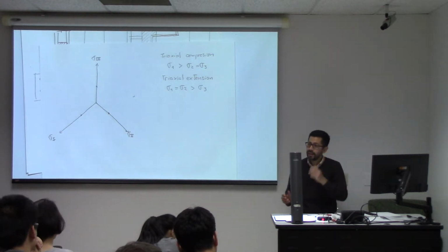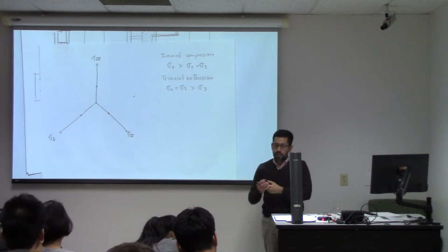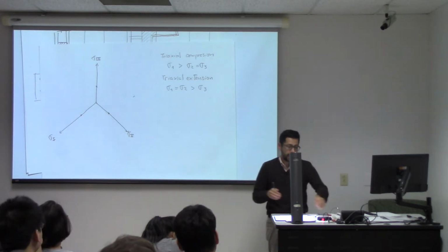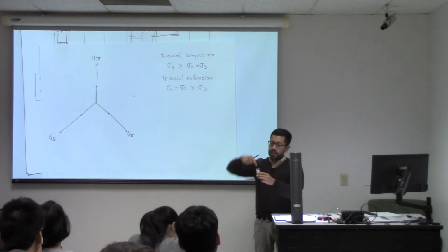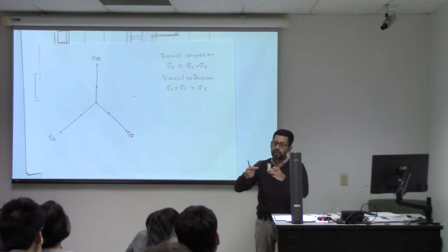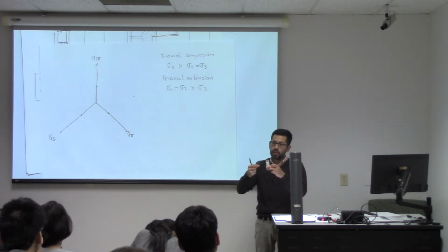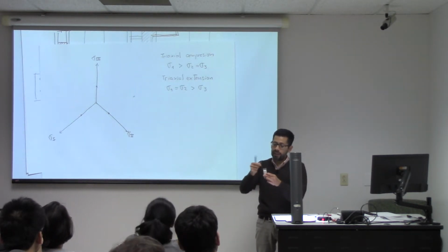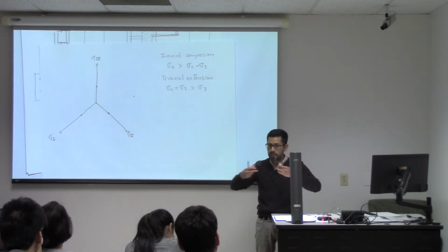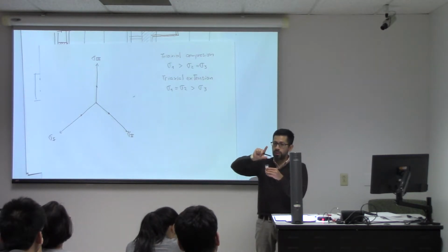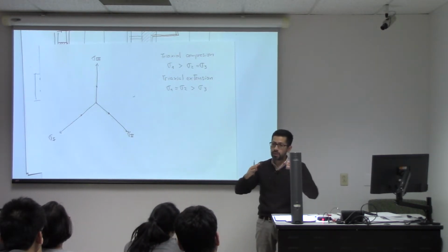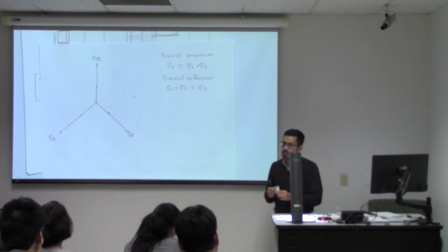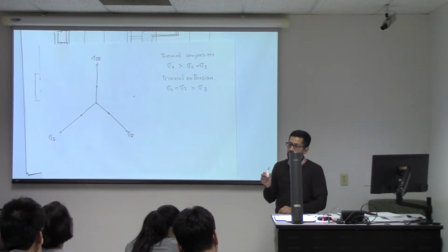So in this case, if I grab this rock in this direction, the stress is going to be lower than the stress in this direction. So you could run such tests and fail this rock by increasing so much the confining pressure, without putting any stress on this side, that it's going to fail by what is called triaxial extension. And the strength is not going to be the same.